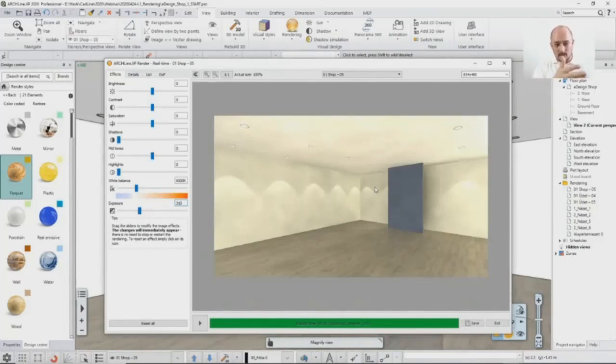The ceiling rendering style that I used is tailored for that. It is making the ceiling brighter than normal, which is what your clients will expect for the renders. They don't want to see the gray ceiling that it really is in reality. If you see it on a photograph, they would like to see something brighter, so you can just apply it. And the same goes for the walls.